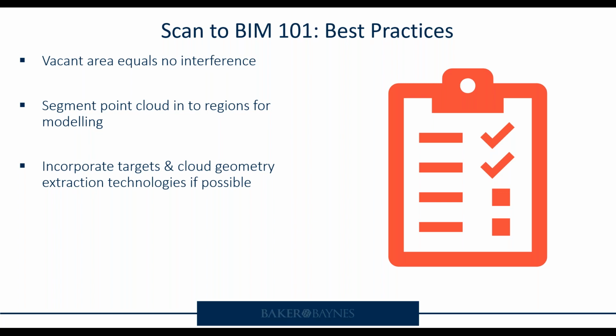So when you do process your data and you upload those coordinate points that have been accurately derived by a surveyor, that will actually tighten up the accuracy and the angle of your scan. So it's a really good process to use. I also use it quite a bit. Even if you're doing drone scanning, control points, ground control points, it works on the same methodology.